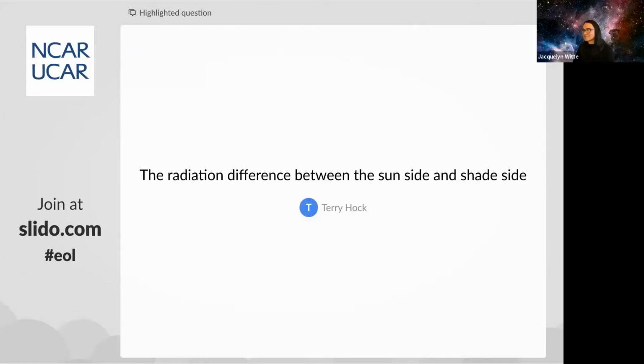There are certain coatings you put on a satellite. Either there's a tape with a foil, or you paint it a certain color, or you anodize it a certain way to either increase or decrease the emissivity of the surface. So it either makes it easier to get rid of waste heat, or it makes it easier to absorb heat. There are extreme temperature differences. When you say radiation difference, yeah, it's kind of hard to radiate toward the sun.